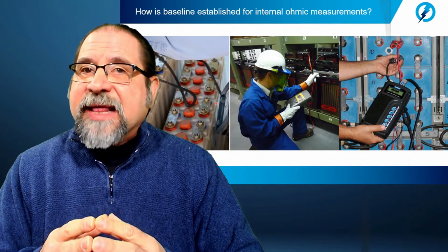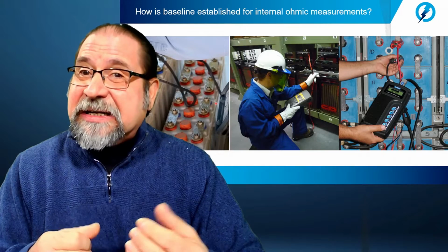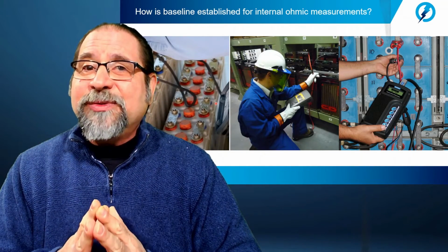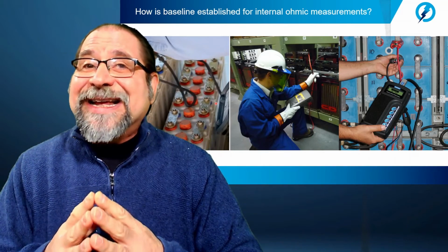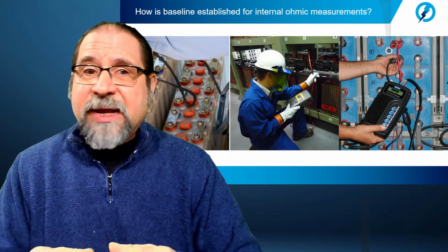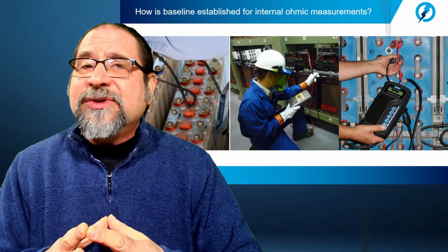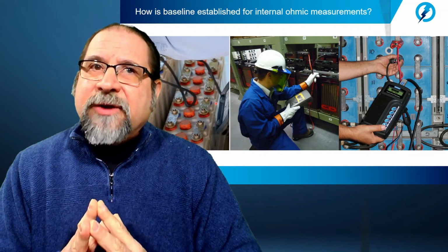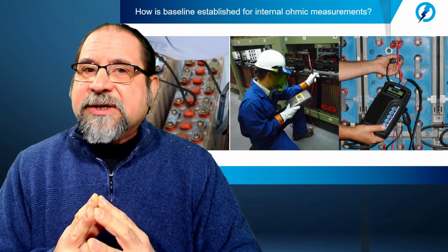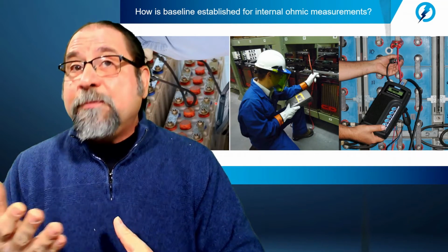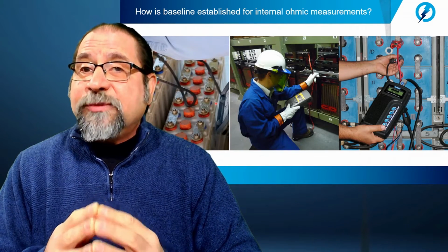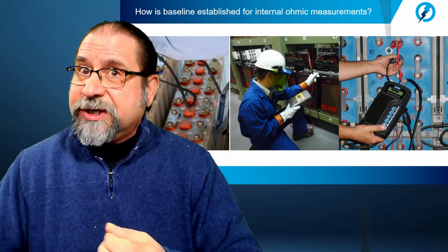Keep in mind that one manufacturer's conductance test equipment does not produce similar results to another manufacturer's impedance test equipment, even though both manufacturers produce ohmic test equipment. Therefore, for meaningful results to an established baseline, the same make and model of instrument should be used.